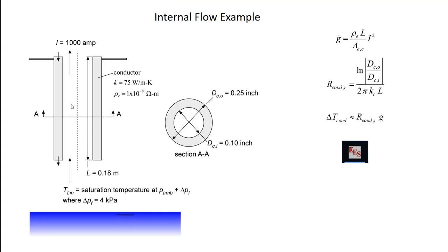So, you know, we just calculated the temperature of the material right there, right? So that's the hottest surface temperature for sure. But if you think about it, there is some resistance radially to getting the ohmic dissipation from the outer radius to the inner radius. And if that's a substantial resistance, then this temperature here might be significantly hotter than this temperature here. So to be safe, I had to think at least a little bit about what this temperature is.